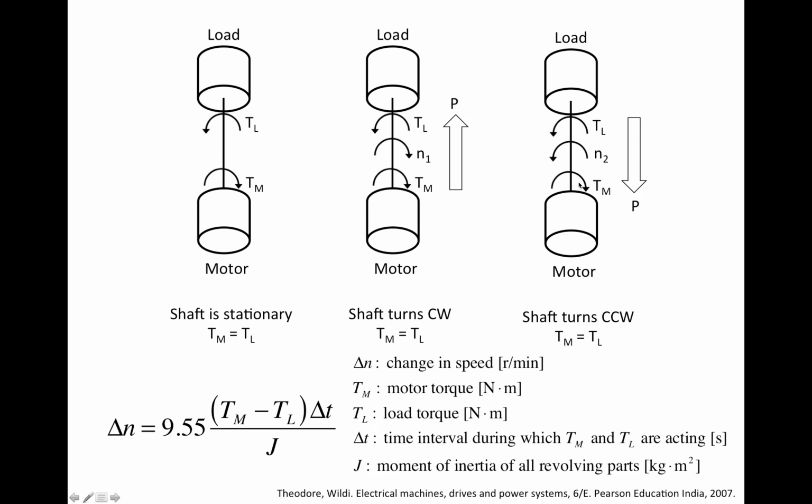And in this other scenario, the torque developed by the motor is actually in the opposite direction of the rotational speed of the shaft, right? And in this kind of case, power actually flows from the load to the motor. The motor is actually receiving energy from the load. And in this scenario, the motor is not really a motor; it's actually a generator. If you actually convert the energy into electricity, then this is indeed a generator, right?